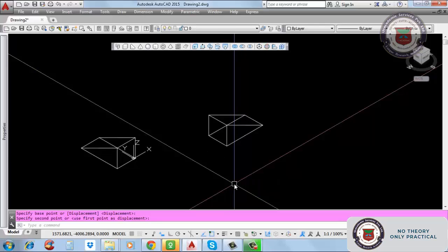That is another option. Suppose you don't want to change your UCS, you can keep your UCS as it is, because the coordinates of objects or projects will be these. It cannot be rotated, because if you rotate it, the x and y dimensions you are giving will change. So we will keep the UCS the same, and after making this wedge we can rotate it up to our requirement.